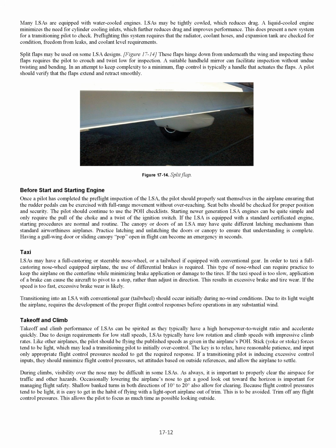Many LSAs are equipped with water-cooled engines. LSAs may be tightly cowled, which reduces drag. A liquid-cooled engine minimizes the need for cylinder cooling inlets, which further reduces drag and improves performance. This does present a new system for a transitioning pilot to check. Pre-flighting this system requires that the radiator, coolant hoses, and expansion tank are checked for condition, freedom from leaks, and coolant level requirements. Split flaps may be used on some LSA designs.